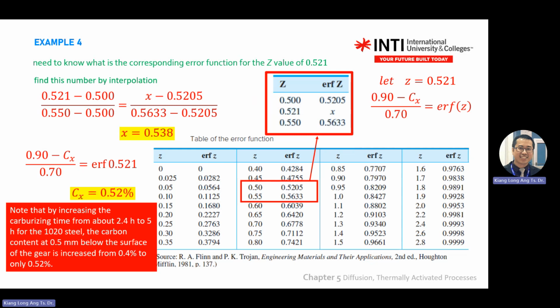Okay, this can be good, can be not good, because more carbon, more brittle. Yeah, metals, you increase more carbon, they become more brittle. It can handle compressive stress, but not very good in tensile. We cannot pull. You pull it, it breaks, or you apply torsion, also breaks. So you need to control the percentage of carbon in metals.